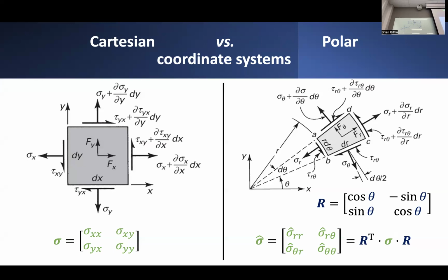So normal components of stress in the radial and circumferential directions. And then the shear components of stress on these faces of the block are precisely the sigma r theta components of stress. Okay. So really, if I'm referring to different components of stress in a polar coordinate frame, they should be sub-indexed not by x and y, but now by r and theta.